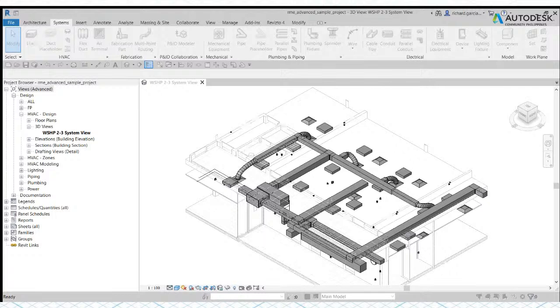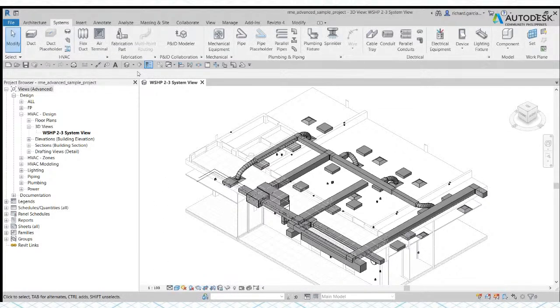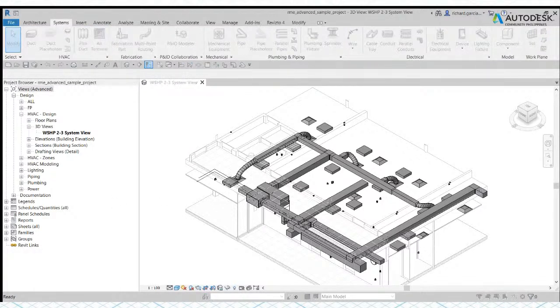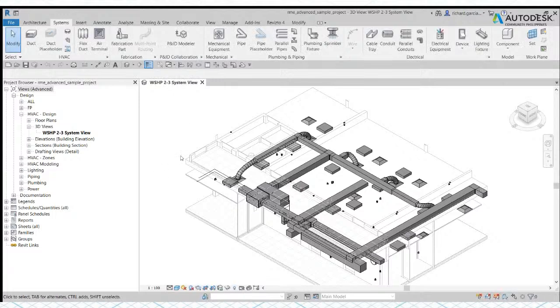If I select none and click OK, and I hover my pointer, there is no information, right? It's up to you, this is for user preference. In my case, I'm not that good in Revit, so I just changed the tooltip assistance to normal. That's how you control it.